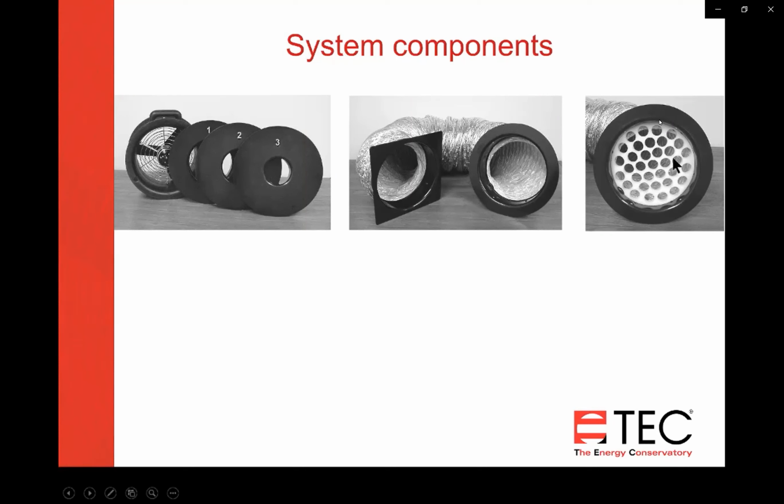When you're doing a depressurization test, the flow sensor, as I mentioned, is inside the flex duct, and you want to be measuring the pressure at the flow sensor with reference to the space the flow sensor is in. And now the flow sensor is in the ductwork. So you need to connect an extra tube that goes to that round transition piece on the flex duct. There's a plastic T there.